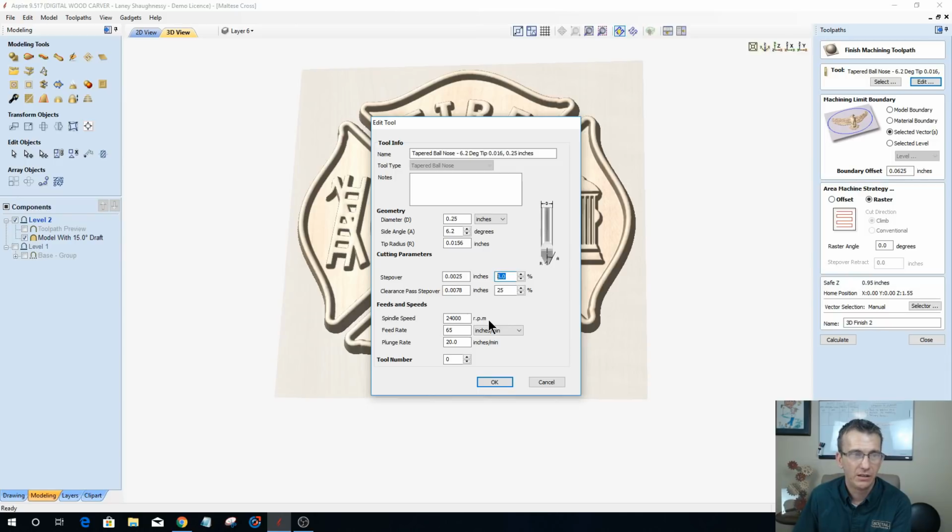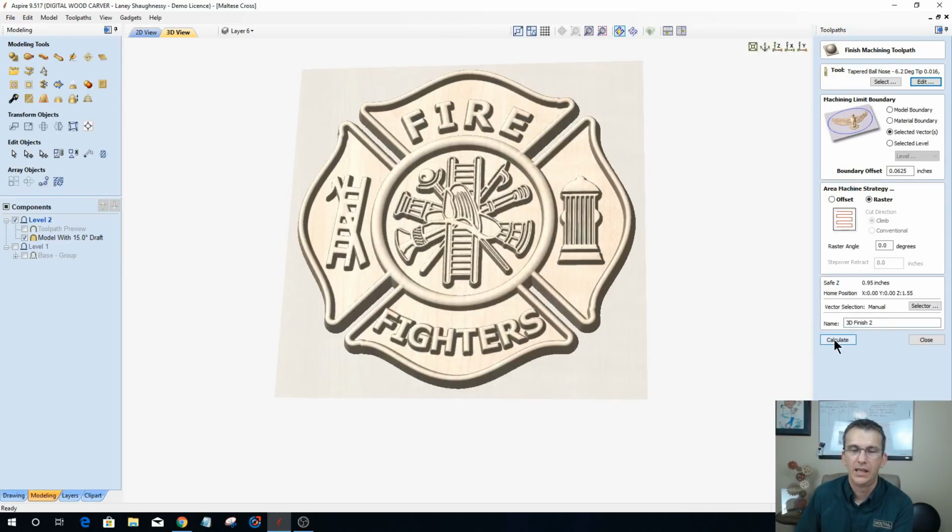On my regular step over, I could probably go from 8 to around 15% step over, and based on that alone, I could probably knock off a third of the time or what have you.